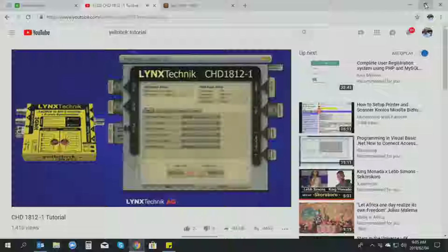The only mechanical physical adjustment on the module is two rotary switches, which are used to set up the analog audio input, and you're basically selecting the analog channel, also the AES channel that you want to embed that analog signal into. You can go across all 8 AES channels, and you can set the input full scale range to line level, or you can even mute it. And again, that's the only real adjustment. Indicators on the module, obviously a power LED, audio present LED, reference present LED, and an HDMI present LED. And that's it, that's the module, self-contained.